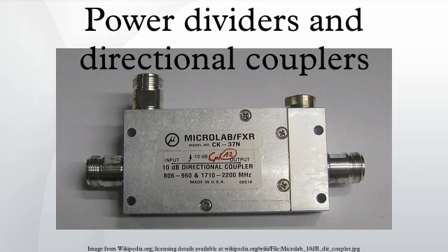In which case the hybrid can be used as a sum and difference hybrid. However, port 4 presents a different impedance to the other ports and will require an additional transformer for impedance conversion if it is required to use this port at the same system impedance. Hybrid transformers are commonly used in telecommunications for 2 to 4 wire conversion.